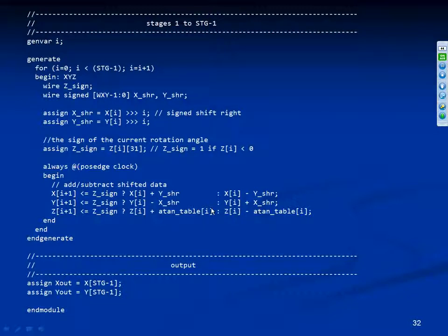Okay. I think what happens is that you get a periodic error if you don't round. The error depends on the phase increment, and you get a periodic error. It's very, very small. But if you do the rounding, then that tends to cancel out, and you don't get the pattern that generates the coherent spur. Yeah, it's hard to know because it depends on which way the rotations go each time and where you start.